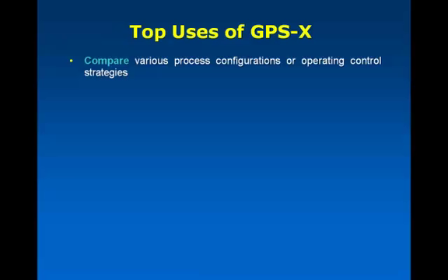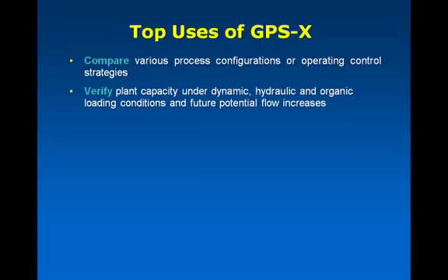For places where there's design going on of a wastewater treatment plant that hasn't even been built yet, and we do quite a bit of modeling of treatment plants that are still in the design stage, this is a good opportunity to use modeling to compare various process configurations. So should I be using a Bardenpho or Johannesburg or an A2O process to do my BioP? Those types of questions can be answered and addressed quite well in the model.